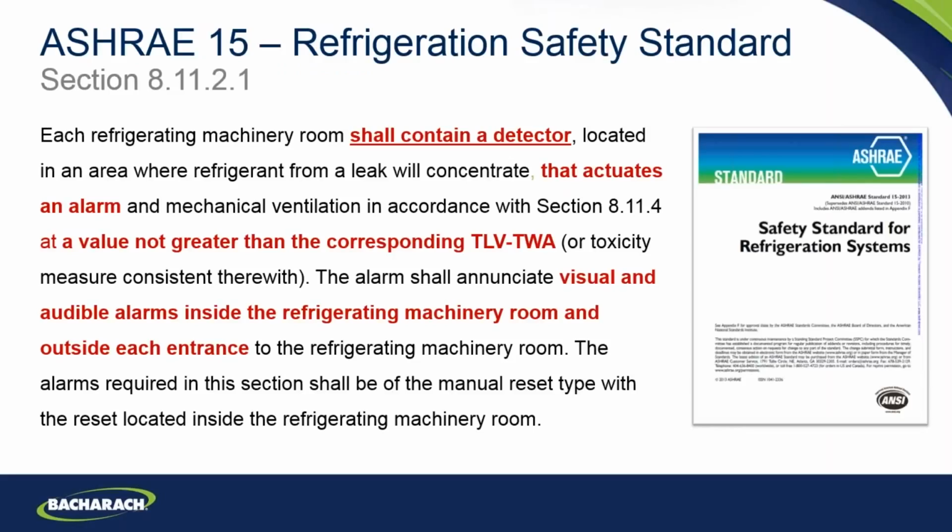So if we look at the safety standards within refrigeration, these don't really drive towards the reduction of leak rate. They're really much more aimed at safety of personnel operating and working with and around refrigeration systems. Now, ASHRAE 15, section 8.11.2.1 specifically states that each refrigerating machinery room shall contain a detector. So if the ASHRAE standard is to be met, then leak detection is essential.